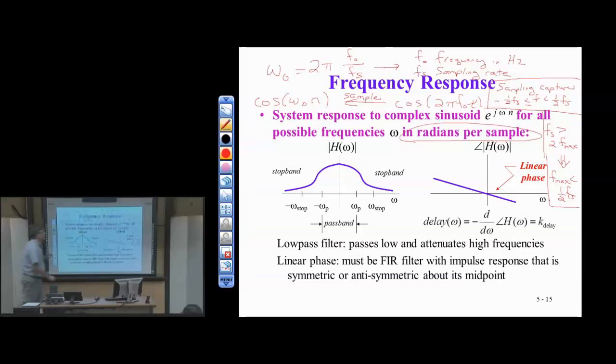Okay, now that's in hertz. Now half the sampling rate corresponds to what content in discrete time? What omega naught? Up to pi, right? So you put in F naught to be half Fs. Fs cancels. Half times 2 is 1. I get pi. So half Fs maps to pi, and minus half Fs maps to minus pi.